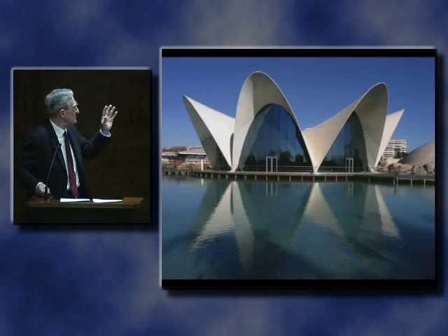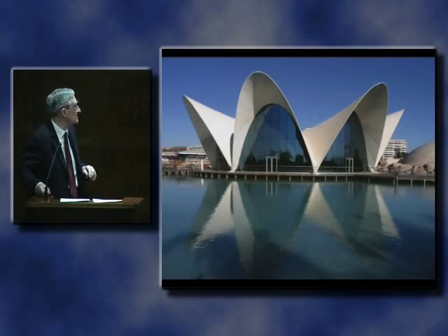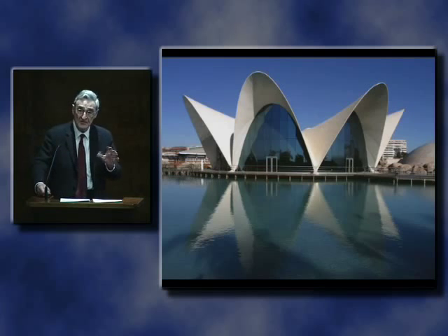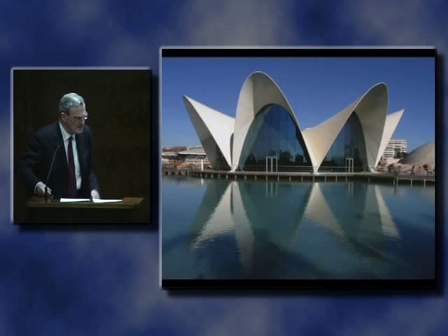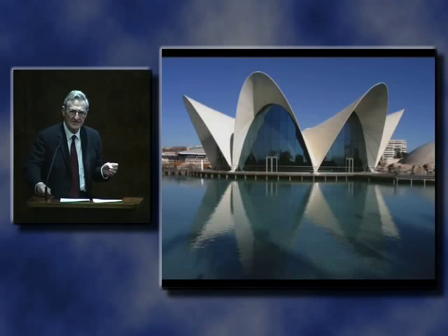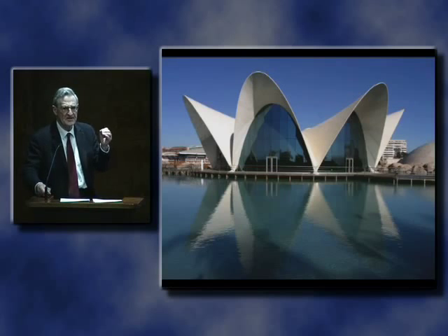Various structures have this sort of arrangement, notably, and again I will show slides of this, the fan vault in English architecture. These vaults of Candela are very much thinner than the 50 we quoted for the radius to thickness for the dome of St. Paul's, which incidentally is the same sort of figure that you have in the construction with 2 bricks in Catalan vaulting, for example, in the so-called timbrel vaulting that you have very much in Spain. Again, a figure of about 50 is right. Candela's thicknesses are 100, 200 or something. They are very, very much thinner.